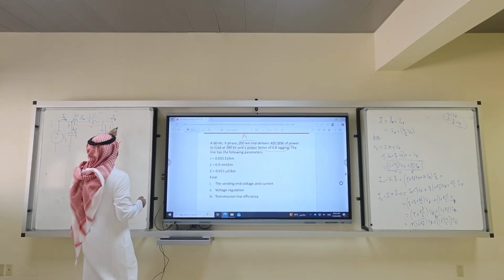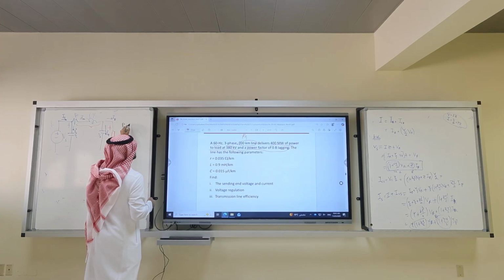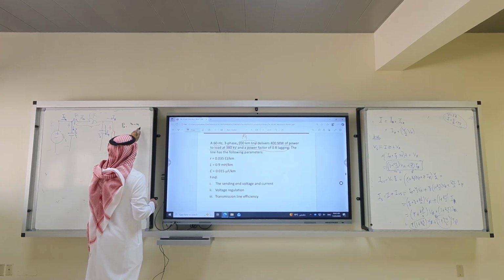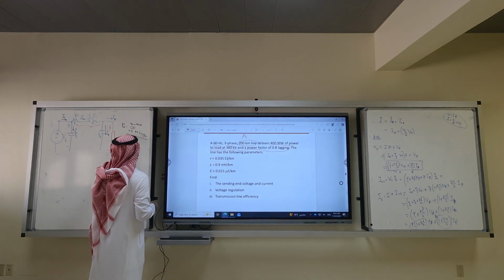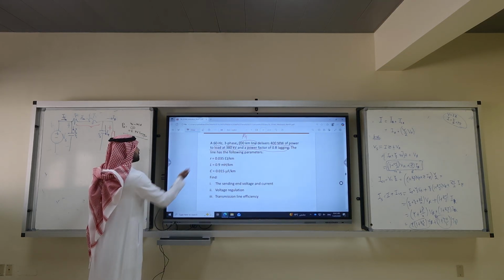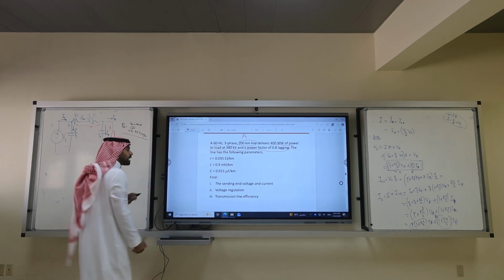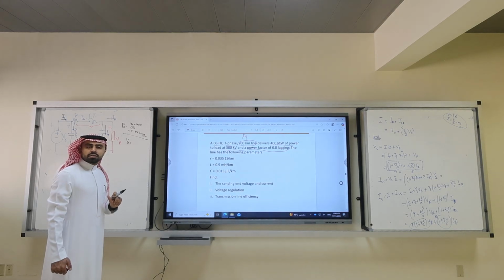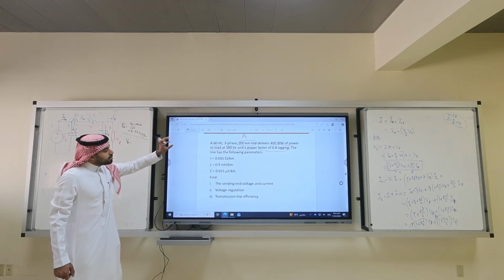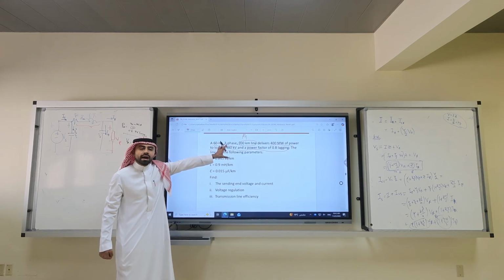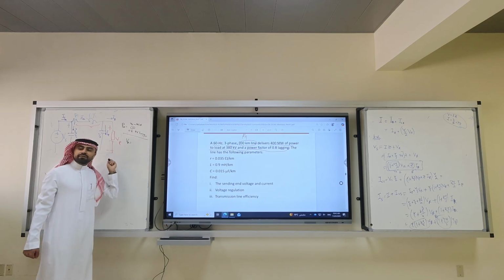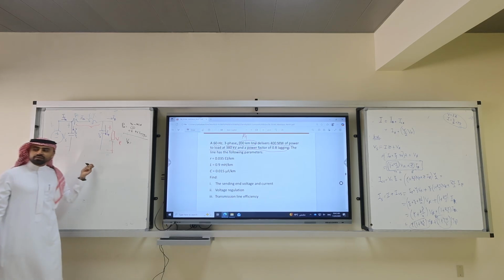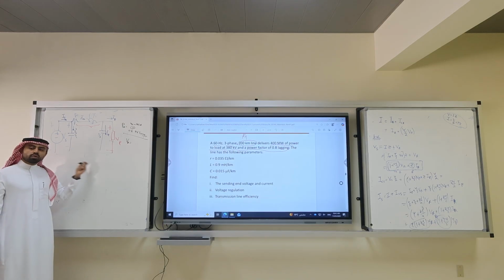So here what is the PR? 400 megawatt at 0.8 PF lagging, okay? What is VR? We love line to line, so VR is 380 kV divided by square root of 3. You understand why? Because the language of communication is line to line. But what we are drawing is the single phase equivalent. Is this a single phase or 3-phase circuit? Single phase. And it's a Y to Y connection.